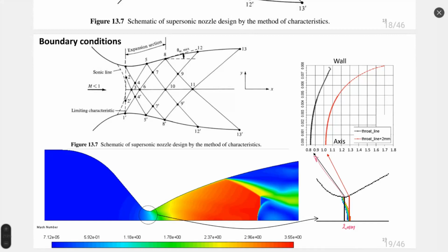Okay, thanks. You're welcome. Please do not forget we have a third method, CFD simulation. You can simulate a nozzle created by method of characteristics and a nozzle created by parabolic functions and see if you have losses, right? If you have some difference in the flow. It is also good to use a viscous model and non-viscous flow simulation.